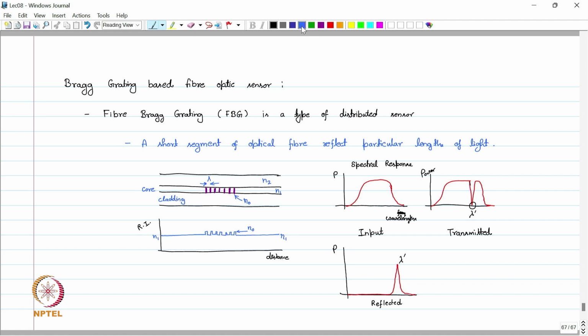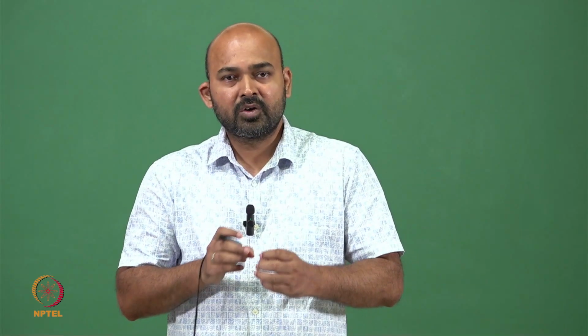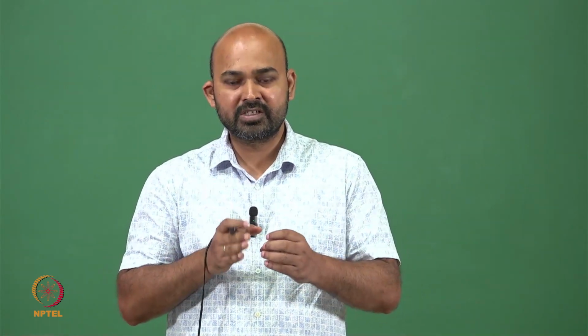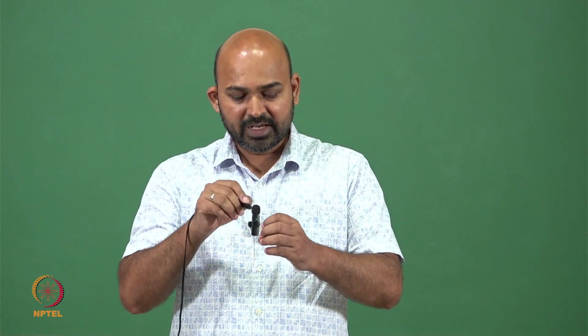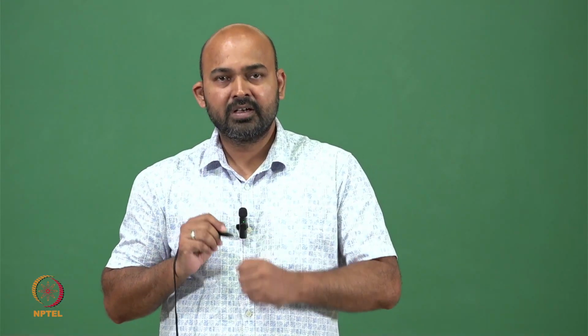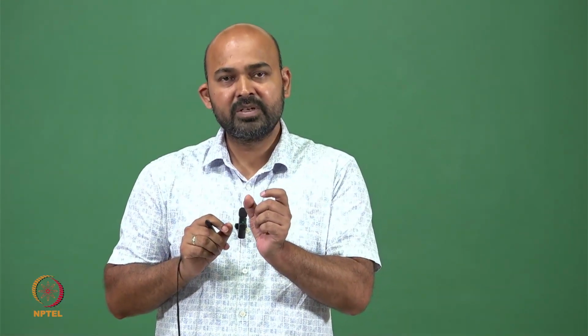And these gratings are very simple to make on the optical fiber. We photo inscribe these gratings on the optical fiber during the manufacturing process itself. We can precisely inscribe these gratings and we know the distance very precisely.